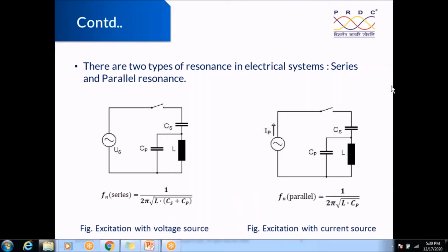The faulty phase can be tripped, and the other two healthy phases can carry some power. From the system point of view, there is then a corridor available with two phases with reduced power flow on that particular line. That reduces the accelerating power for the synchronous machine rotor, thereby improving the stability, because you will have some more margin. Okay, so that is the idea to have a stable system, so we adopt single phase tripping schemes. This is what we do intentionally to create this uneven phase operation.